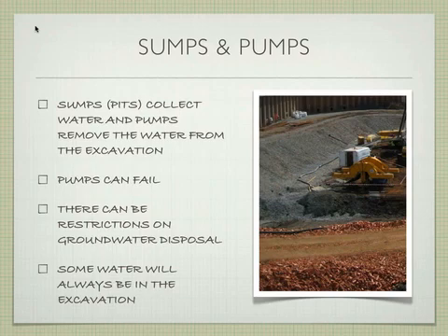The problem with this is that your pump can fail. The electricity can go out. You can run out of gas if it's a gas pump. Your generator can fail. There's lots of problems, and if that happens, you have water on your site, you can't do work. It's a problem. Also, you're pumping all this water out, you have to get rid of the water somewhere. So depending on where you're working, you can't just open the sewer and pump the water into the sewer. You have to figure out how you're going to get rid of that water.